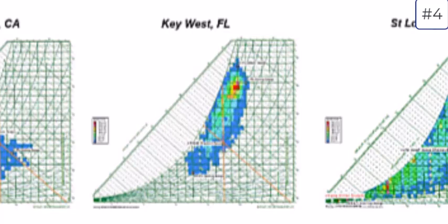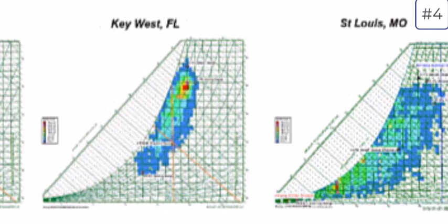For Florida, we would expect the fixed dry bulb high limit somewhere around here. And you can see that there's not many bin hours to the left of this line where we would actually be economizing. So having this particular economizer stuck at the minimum position would have a very limited effect on the operation of an air handling unit in this climate.